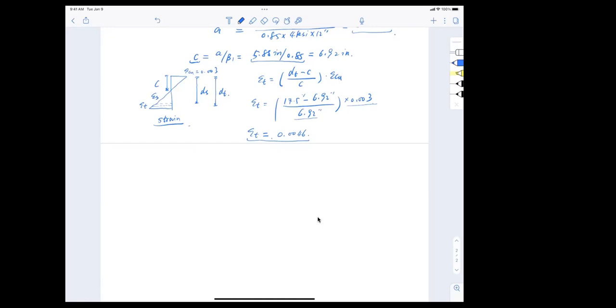I don't feel amazing because it's below that 0.005 number, right? You're exactly right. You're a wonderful civil engineer, right? So you saw this, your heart sunk and said, oh crap, I'm just a hair less than the tension control limit. This tells me that I'm in a transition zone. Okay, wonderful. Thank you so much. You're officially off the hook now, sir.